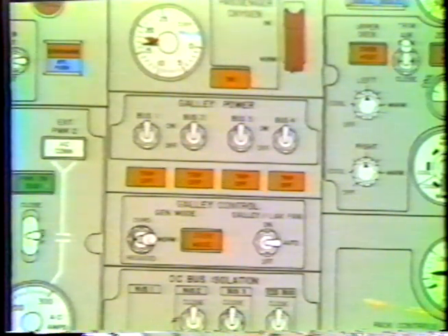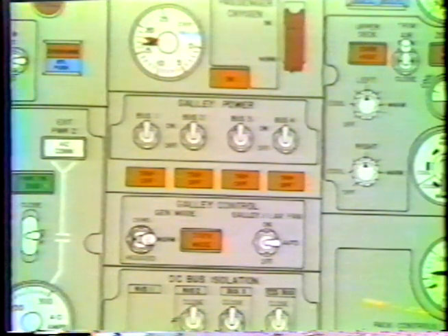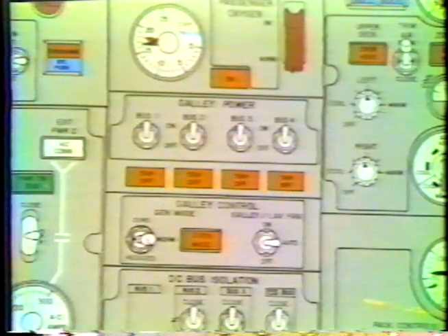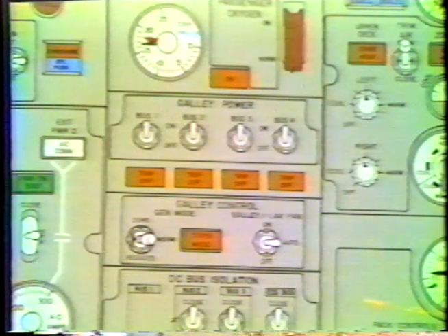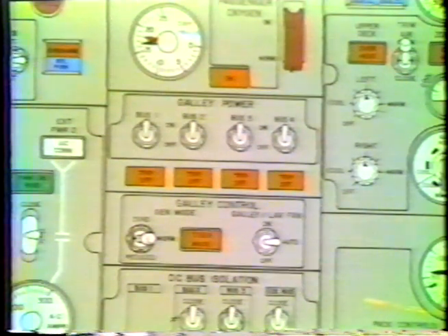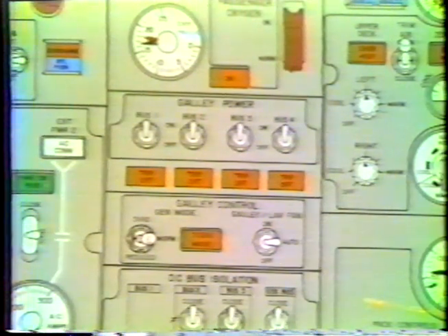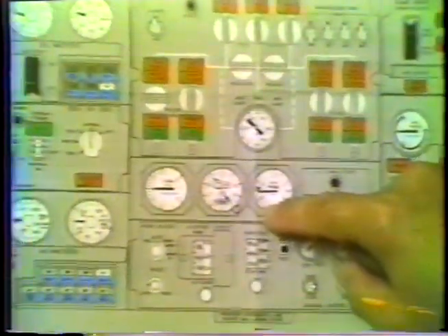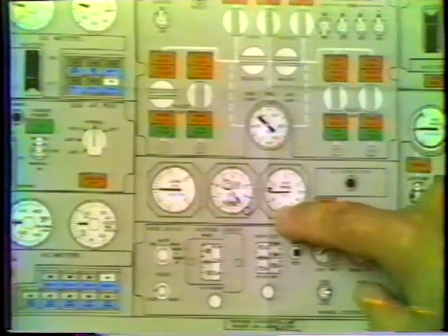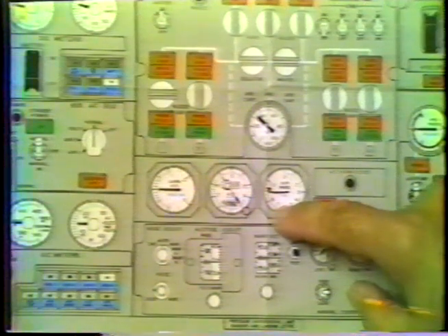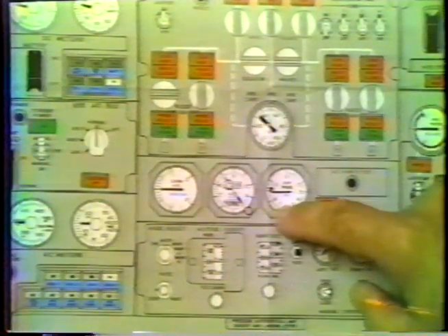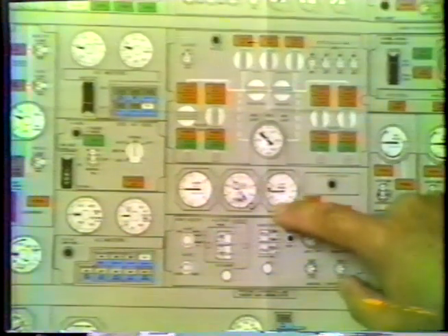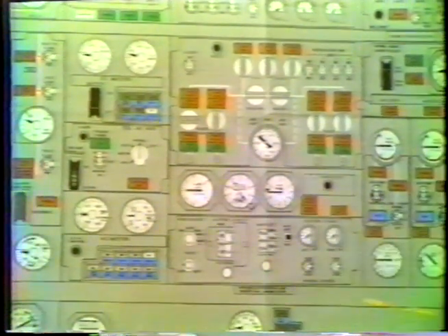In automatic, it operates at lower cabin pressures, and as you get to a higher and higher altitude, when the pressure differential in the aircraft on the pressurization gets approximately 6.8 psi, this Lav galley vent fan will stop and open another overboard vent in the middle of the fuselage. And then as you descend in altitude and the pressure differential comes down, it will start up again.